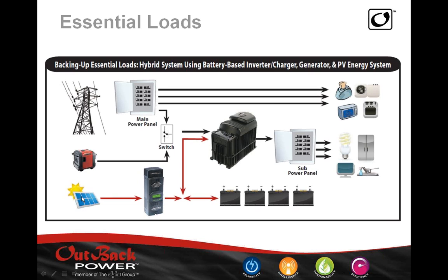And here at the bottom we have our PV modules feeding our charge controller. The charge controller then is doing the charging of the batteries, and if the batteries in this case are fully charged, then the current that's being harvested will be going into the inverter and onto the loads. So here we have two situations.